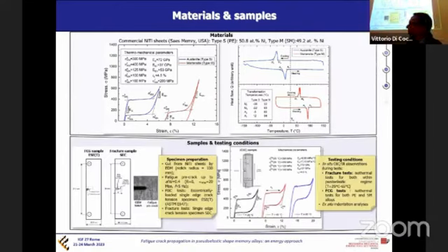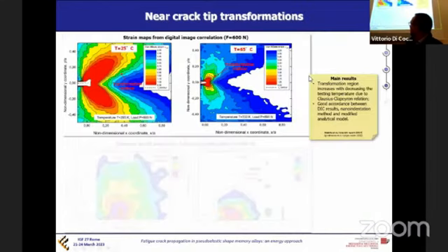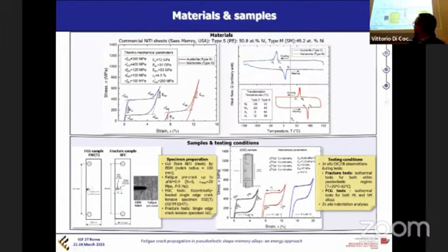We use a single edge crack sample obtained from commercial nickel titanium materials. And we have also tried to capture the effects of temperature, to capture the effect of thermomechanical coupling, because when increasing the temperature in a pseudoelastic material, the stress plateau increases significantly, with a ratio of about 10 megapascal per Celsius degree.